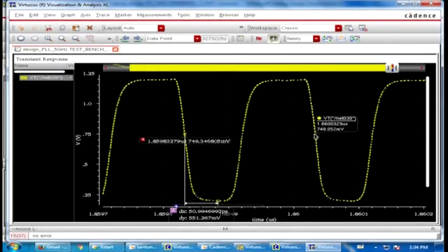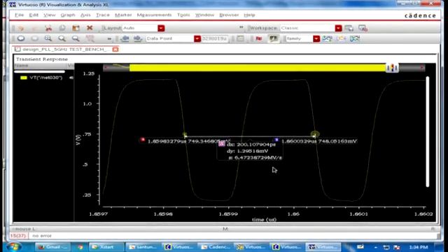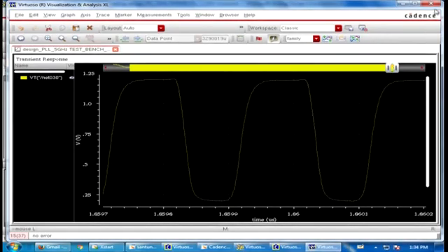That will drive my mixer. In this case, almost 200 picoseconds means it's 5 gigahertz. Which one is 200? You can find out the time period is 200 picoseconds. So it is almost 5 gigahertz. So that is the free running frequency of the oscillator.